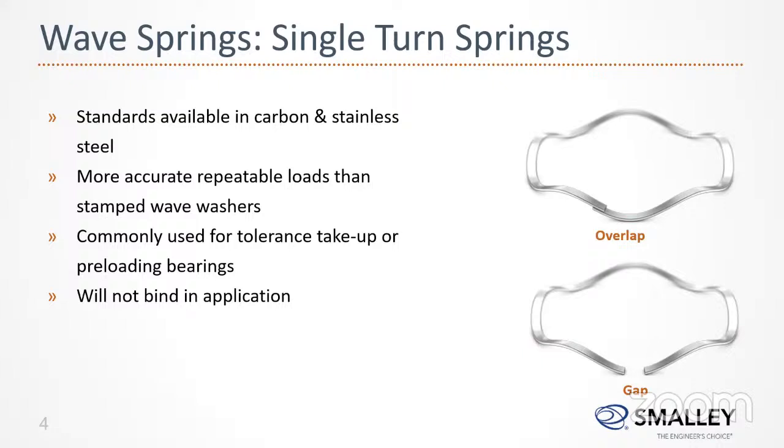There are two methods to manufacture a single-turn wave spring. Either you can take a sheet, stamp it, and then form the waves. We don't make stamped wave washers, because in a stamped wave washer the grain structure moves in one direction in the sheet. When you are stamping, you are damaging the grain structure. That will reduce the lifetime, and a component made by the stamped process will reach fatigue very easily. It will not provide the spring force until the end of the assembly's life cycle.